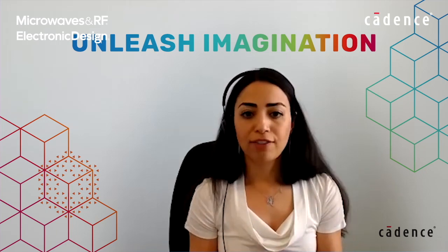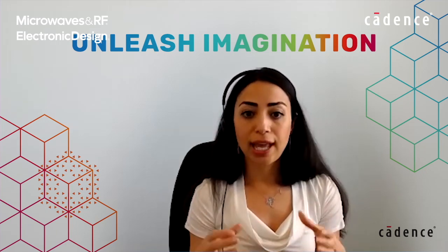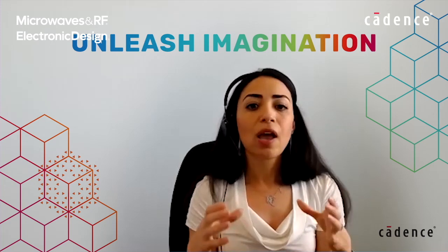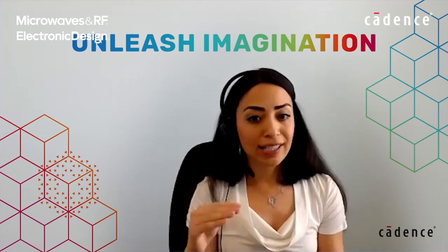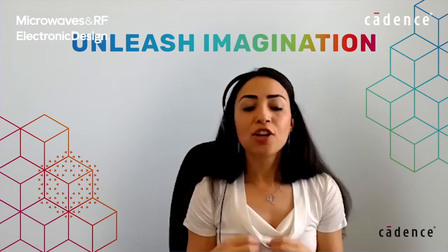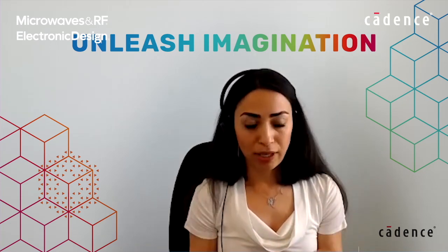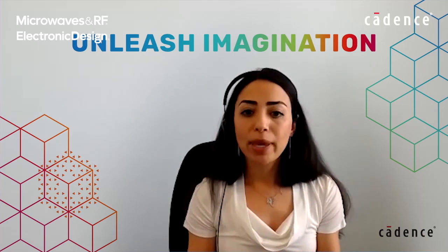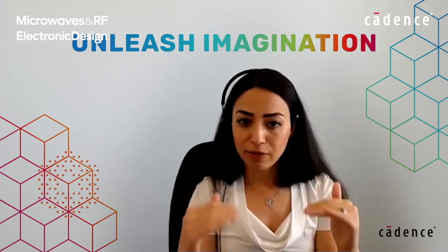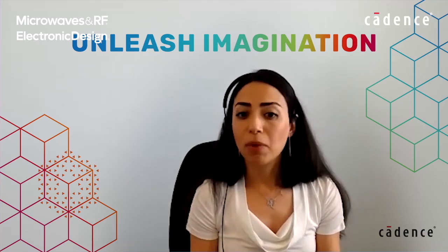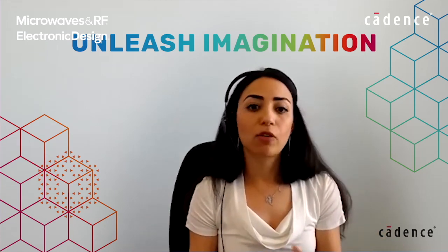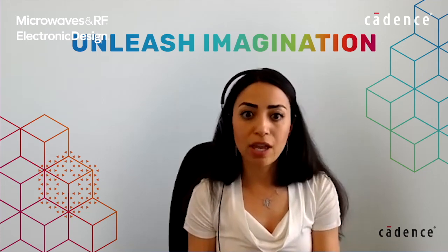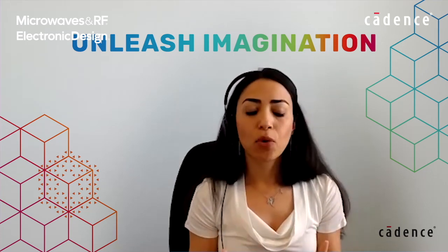So one thing we have to do is to have an understanding in early design of, for example, what IP we want to put on what chip, and how that will impact the performance. So this is one of the important things. Or the other thing is how big we want our package to be to help us with all these thermal issues that we might have in a chip. Or how big should our PCB be? Or where should we put our thermal vias? So all these analyses are important to do.